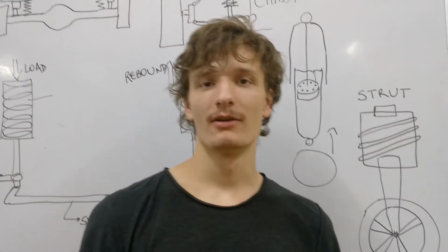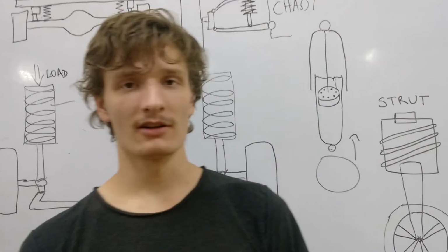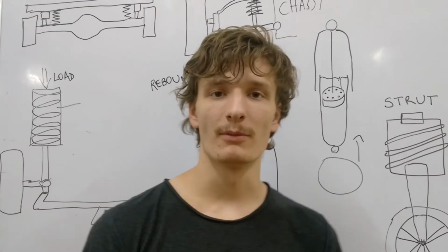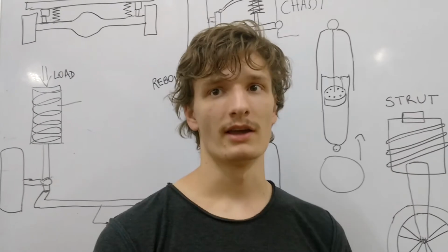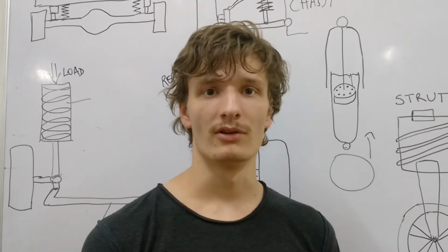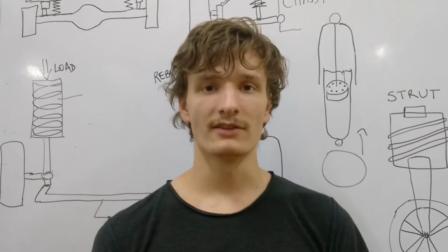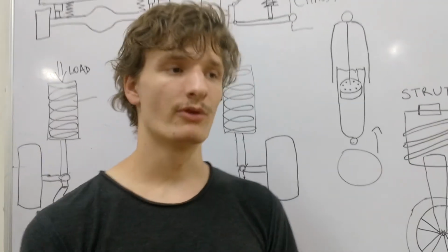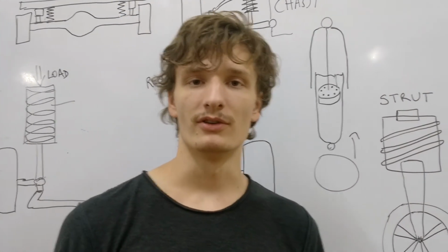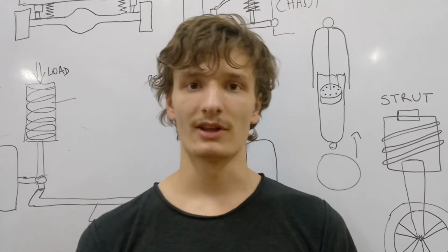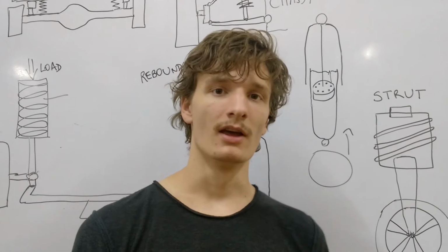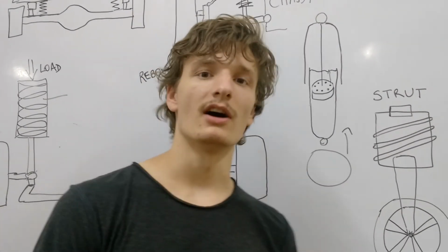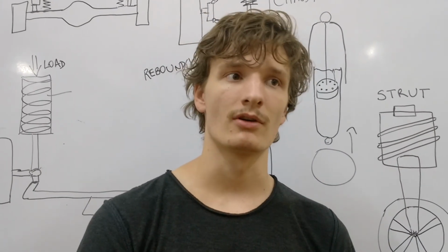Okay, the newest and most modern technology of suspension goes in the development of the magnetic damper control, where you can electronically via magnet control the settings of the damper, and to an air ride system where you get an air suspension. With those two systems, it's possible to basically level the car at all times and absorb the bumps basically completely. And this is what's actually used in the newest luxury cars, and in the future will probably also be in common cars.